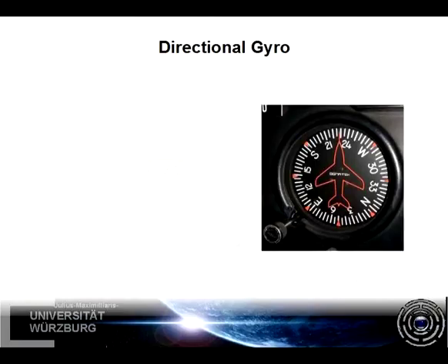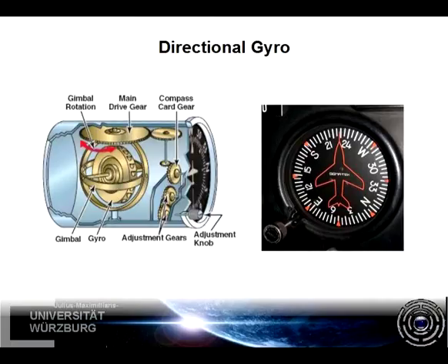In the cockpit, the pilot sees a heading rose that he can freely calibrate with a knob to set the current heading. Usually he would do that in straight and level flight, where the magnetic compass is most reliable. When the aircraft makes turns, the indication will show the changes to the heading precisely and without the flaws of the simple magnetic compass. This advantage is gained by using a gyroscope that is mechanically tied to the heading indicator and sensitive to movements around the vertical axis of the aircraft.